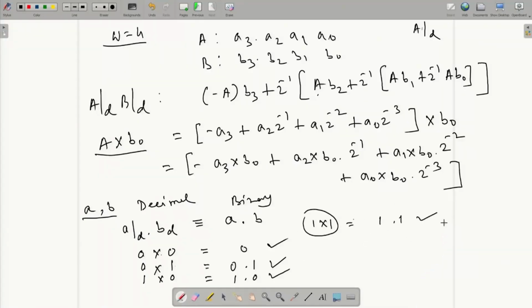So, this is satisfied, which means if I give you two binary bits A and B, in the decimal domain, if you multiply their decimal values, where binary 0 remains decimal 0 and binary 1 remains decimal 1, it means in the binary domain you treat them as binary bits and do an AND operation between them. Whatever binary variable you get out of it, that is A dot B, will have the same decimal value as the product of the decimal of A and decimal of B. So, in the binary domain I simply have to represent that as A dot B, all right.